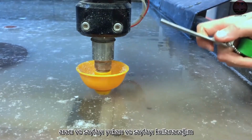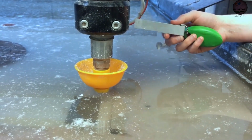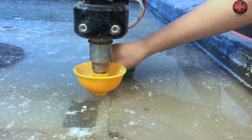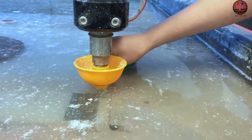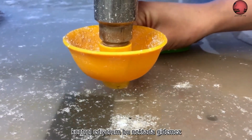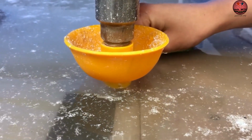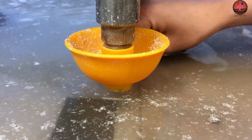And now I'll use this tool and I'll use the page up and page down keys on the keyboard to do fine control of the height. So I'll start lowering it using page down and I'll sweep the measuring tool under the nozzle. You want to make sure that there's no resistance. So I'll continue lowering it and sweeping and checking. See, at this point, it can't go any further. So I'll need to use page up to lift it until it sweeps with no resistance.